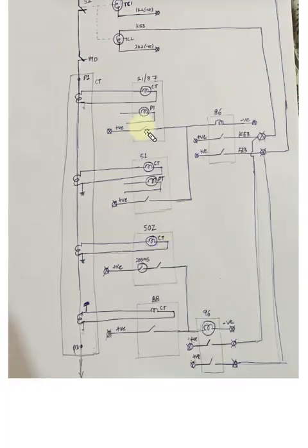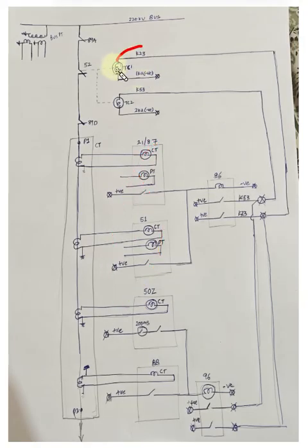Okay, similarly, when the distance relay fails, for that we use a backup relay. Here we have shown an overcurrent relay. Similarly, current and voltage are extended to the backup relay, positive is given to one end of its output contact, and when the backup relay operates, the positive is again extended to the master trip relay. Okay, so this whole procedure of tripping takes place in around 50 milliseconds, 20 milliseconds for the operation of the relay, and about 30 milliseconds for the operation of the breaker.